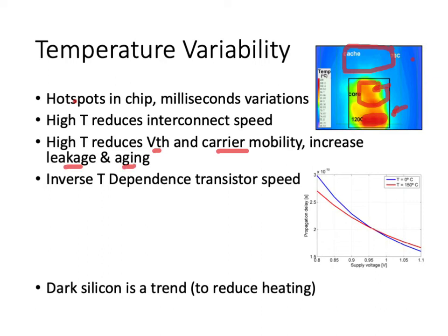But I'd first like to draw your attention to this graph here. As you can see, this is the speed as a function of supply voltage. The delay, of course, is minimum at a higher supply voltage, because we're applying more voltage, we have more current, and more current means we can charge and discharge the logic gates quicker. As the supply voltage reduces, the delay increases proportionately.